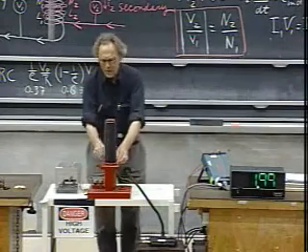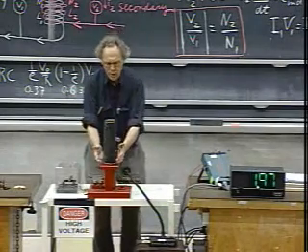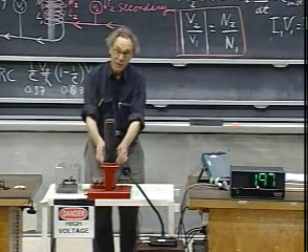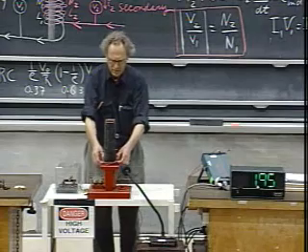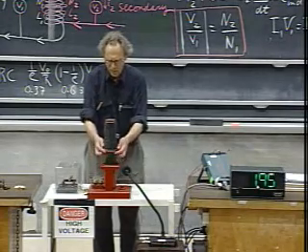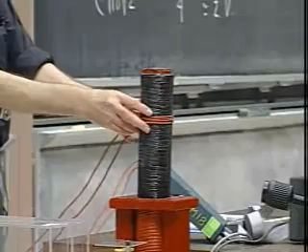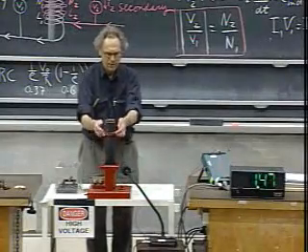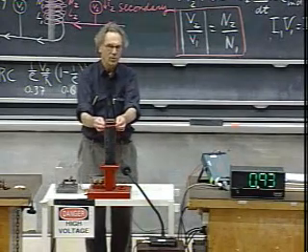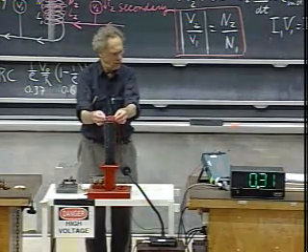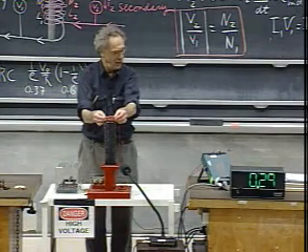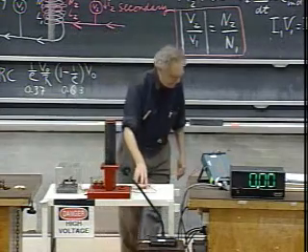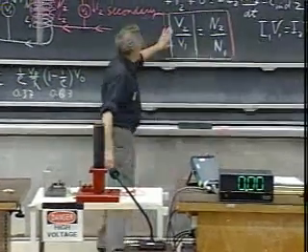What I will do now, I will move it up a little. And when I move it up a little, the flux coupling of the secondary is not ideal anymore. And so you expect that V2 will go down. Just move it up a little along the primary, and you see the value goes down, because now the flux coupling is not ideal. And if I bring it further out, flux coupling becomes hopeless, and when I bring it here, the flux coupling is so poor, but I still get 0.3 volts, by the way. So that's the first part, to show you that this is indeed quite accurate.